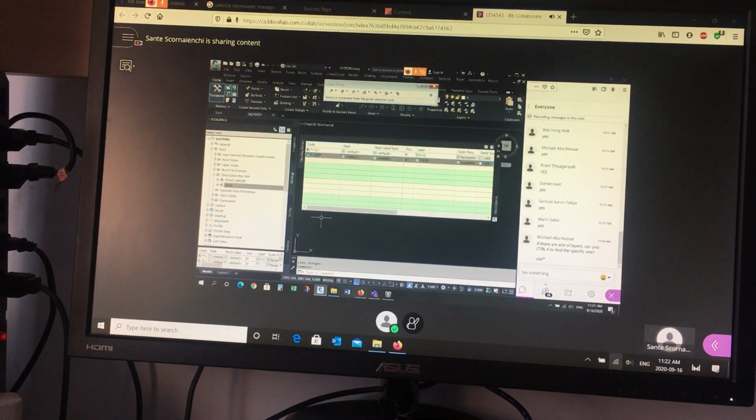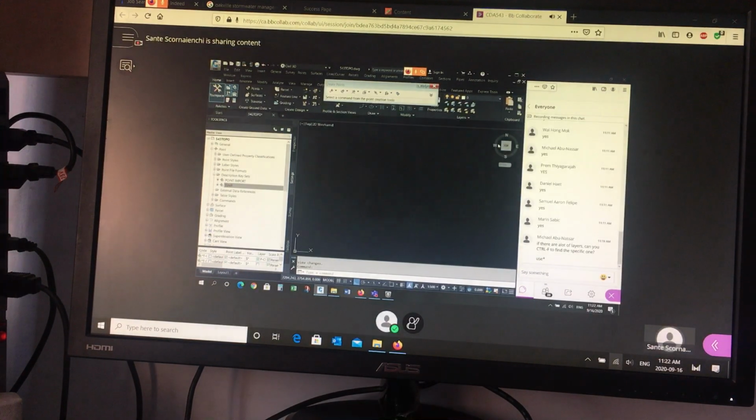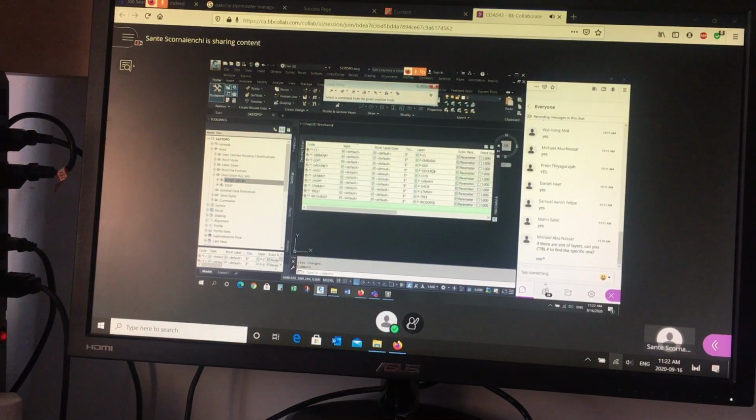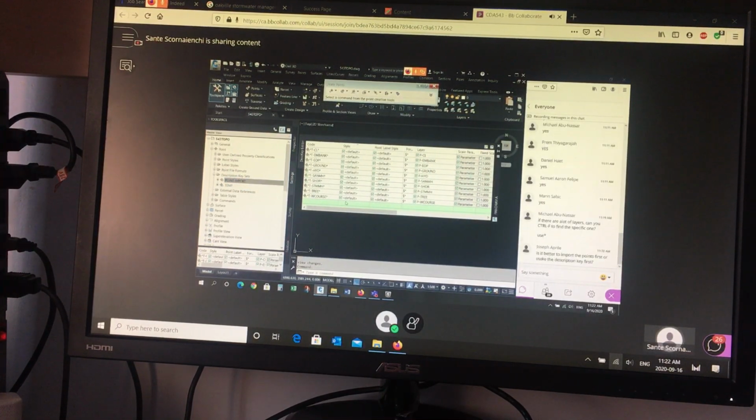So I'm not going to program all of it. I've already done this. It's like a cooking show: I'm showing you one turkey, and I'm going to pull the other one out of the oven, already cooked. That's how you create it. But I'm going to use this point import function. This is already programmed. Let me show it to you. Edit the keys. Again, T dash descriptions go on the P dash layer. Make sure the style and the point styles are all on.